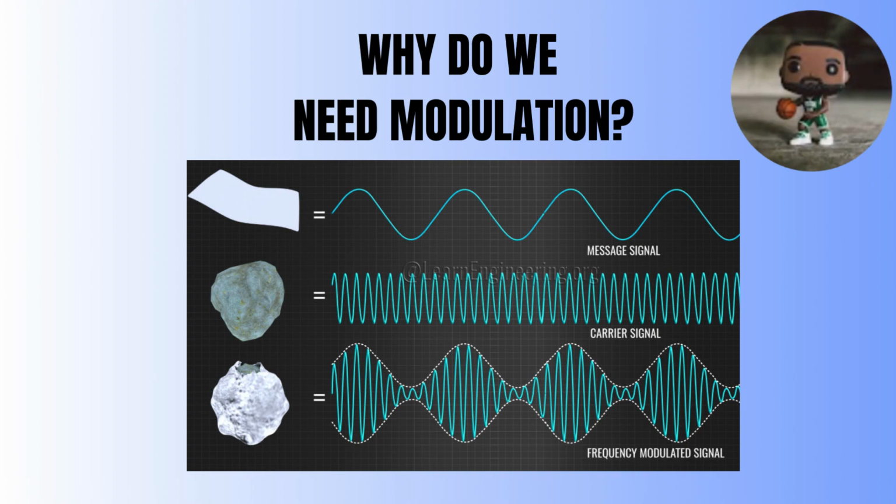So, why do we need modulation? It is because in real life communication, low frequency signals like voice cannot travel far efficiently. Modulation allows us to shift the information onto a high frequency carrier so it can be transmitted over long distance. You can try to imagine the message signal is a paper and the carrier signal is a stone, and you use the message signal as an envelope to envelop the carrier signal, which is the stone.